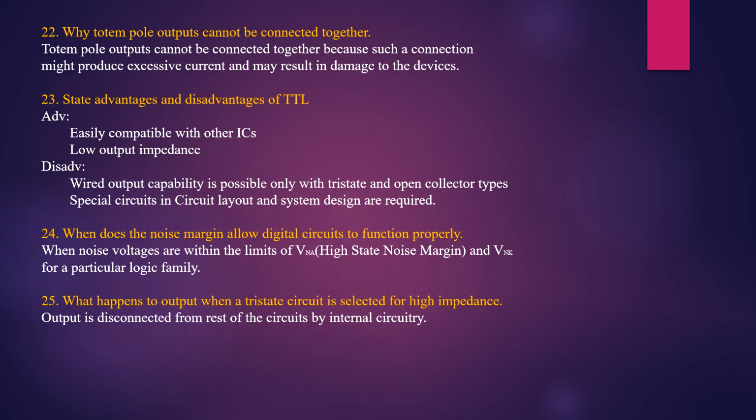24th question, when does the noise margin allow digital circuits to function properly? The noise margins are within the limits of the high-state noise margin and low-state noise margin of the particular logic family, and in between these states it allows. The 25th question, what happens to output when a tri-state circuit is selected for high impedance? Output is disconnected from the rest of the circuits by the internal circuit.